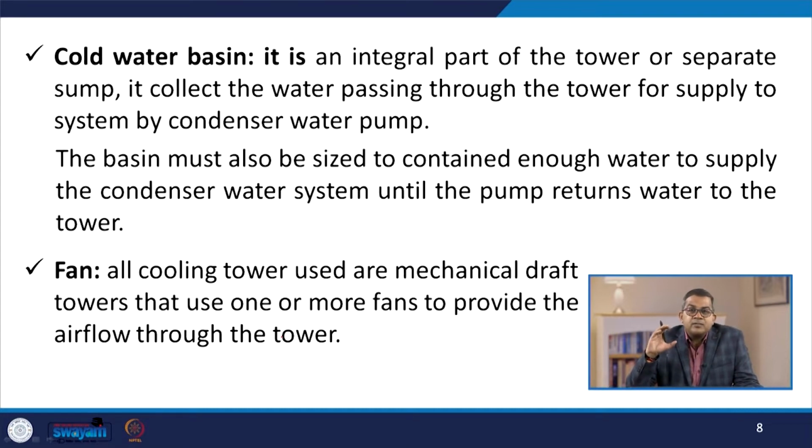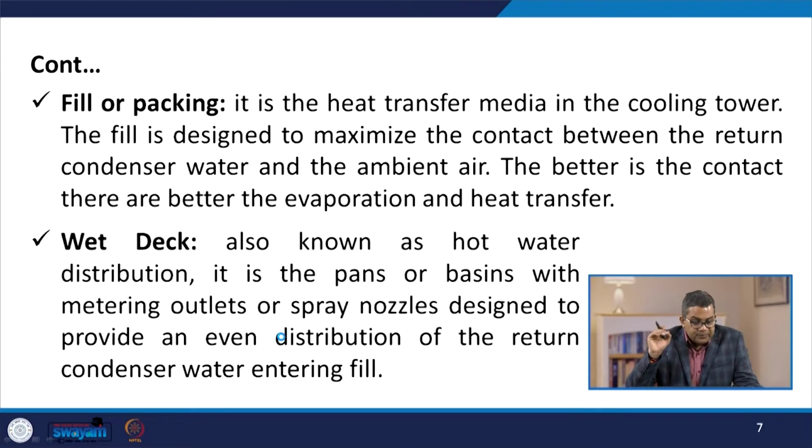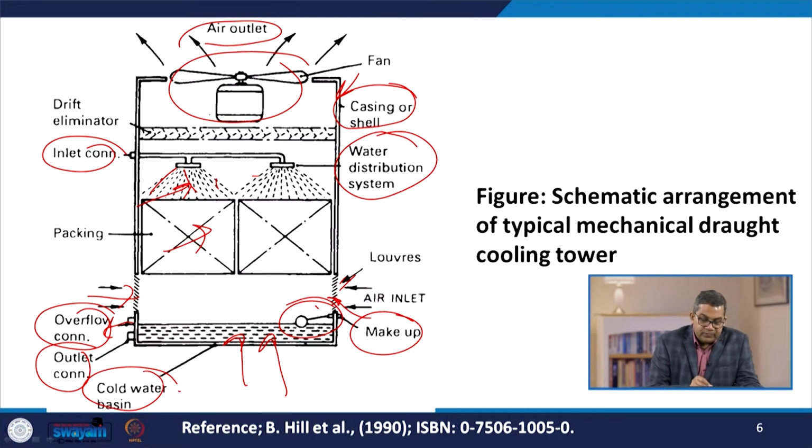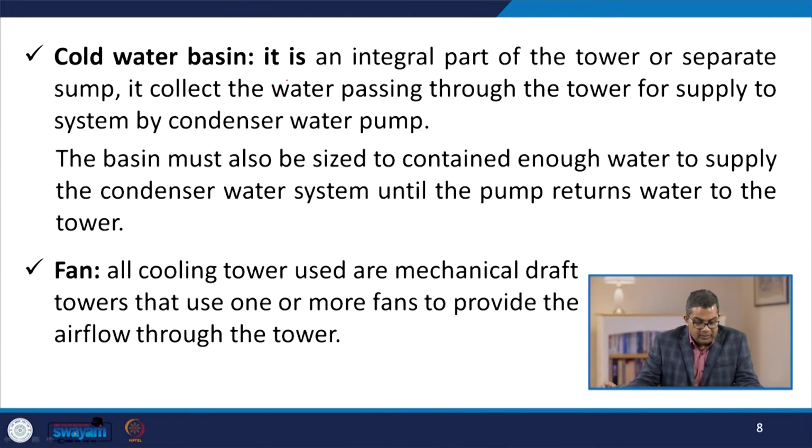Now, this basin must also be sized to contain enough water to supply the condenser water system until the pump returns water to the tower. Then there must be a fan. Here we have the fan. Now, all cooling towers use a mechanical draft tower that uses one or more fans to provide the airflow